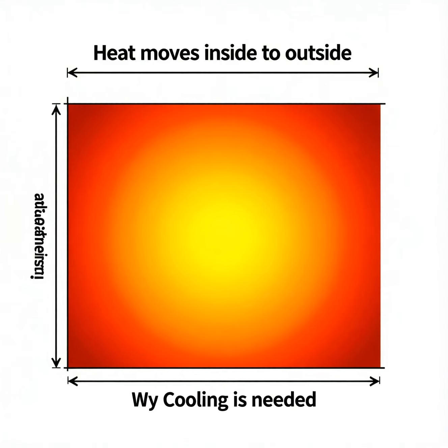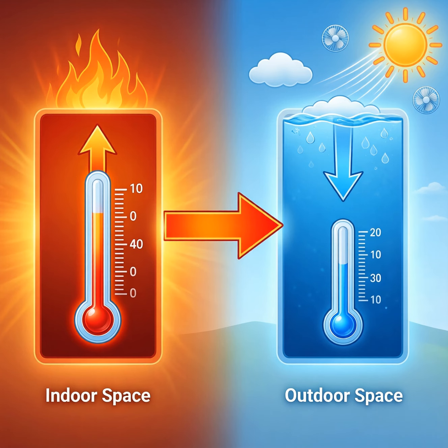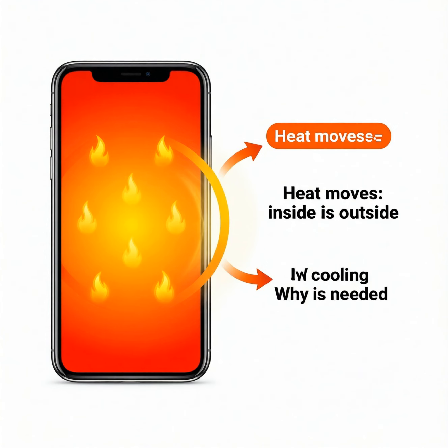Inside the unit, a compressor squeezes low-pressure refrigerant into hot vapor. That vapor rushes through copper tubes to a condenser coil outside. Fans blow air over the coil, pulling heat from the gas and cooling it back into liquid. The liquid then drops in pressure at an expansion valve, turning cold again before entering the evaporator inside your home. Here, warm indoor air passes over the cold coils, giving up its heat to the refrigerant.